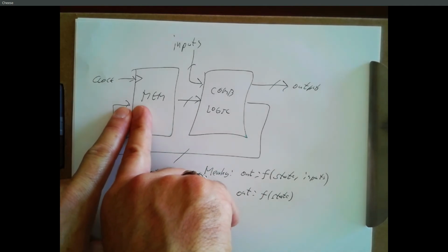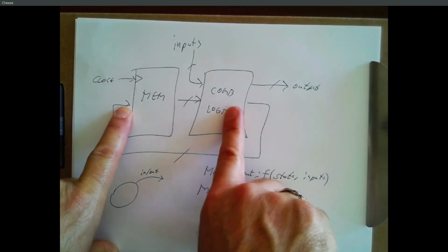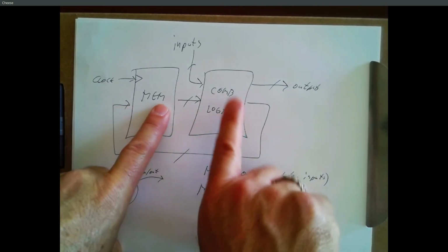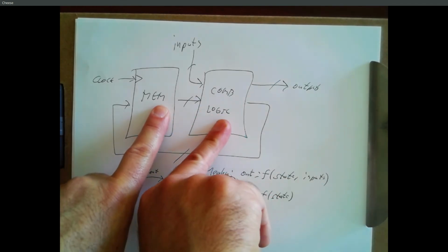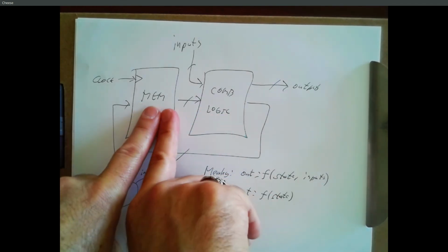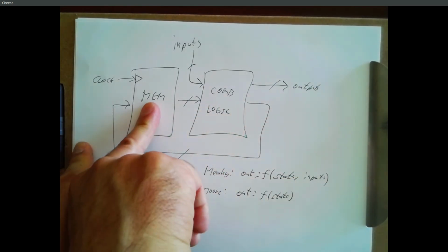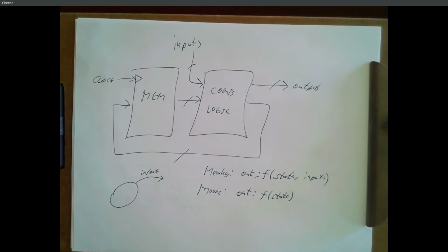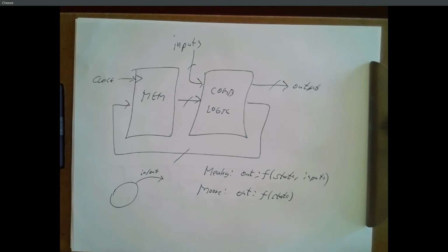And then you can tick the clock, and if the hold time was long enough that the outputs might change again, you need to take the hold time into account. But usually we can ignore the hold time, because once the outputs change, it's going to take a while before those changes trickle through and we change the inputs. That's usually longer than the hold time. So it's really the setup time plus the propagation delay. That's how much time you need between ticks. So that's your minimum period. Reciprocal is your maximum frequency.